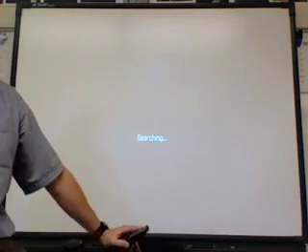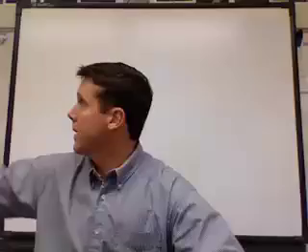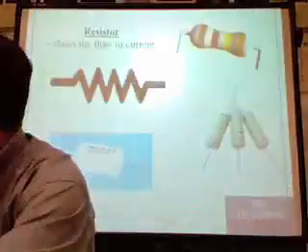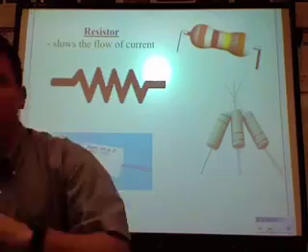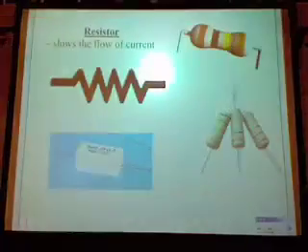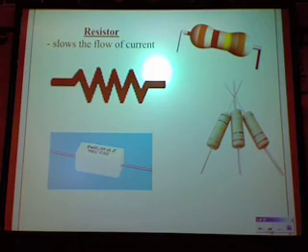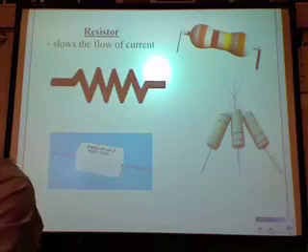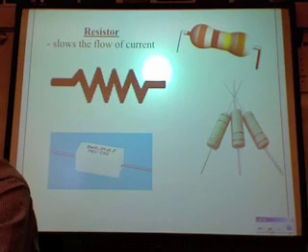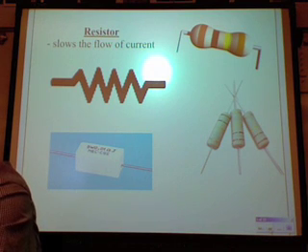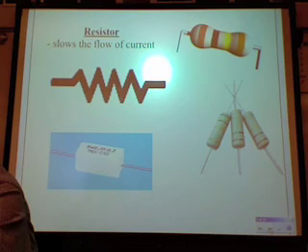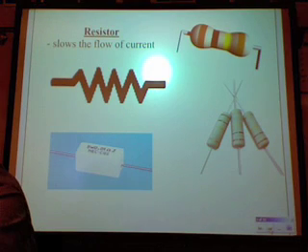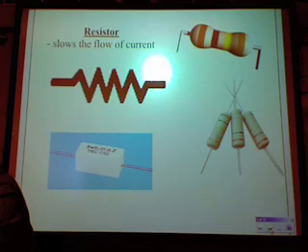That would be the colored bands tell you that. Okay? So you can look at the colored bands. If you look up on the TV, you'll see what I'm talking about, the colored bands on these. And when we build our circuits, you'll have to identify which resistor is which based on these colored bands. There's actually a resistor color code that we use. So I do want you to add that to your notes, that you can tell the amount of resistance by the colored bands.